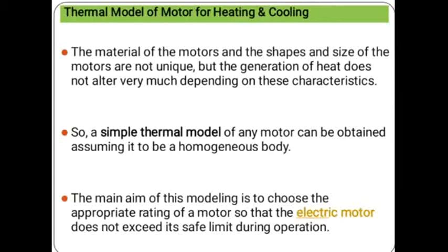Using these assumptions, a simple thermal model of the motor can be obtained. This thermal model cannot be said to be perfect, but it is suitable for electrical drive engineers to select the motor rating for given applications, ensuring that temperatures in the various parts of the motor body do not exceed their safe limit.